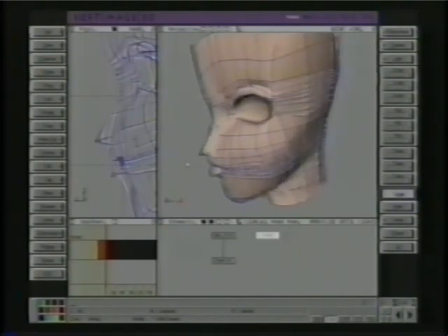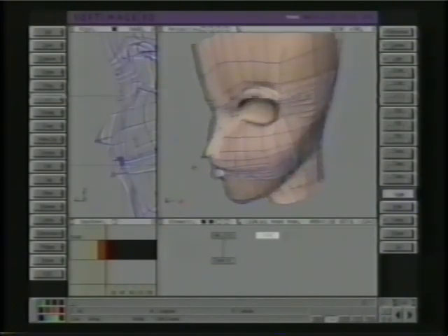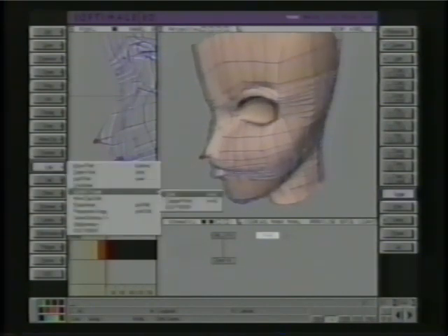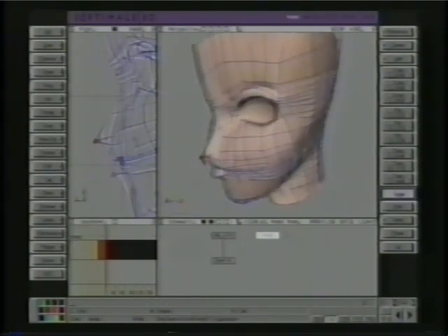Like I mentioned in the curves section, with a NURBS curve or NURBS surface, you can weight the surface toward the control mesh vertices. So for instance, I'll select those two, go into Edit, NURBS Weight, Tagged Points, and then drag. You can see that get pointy around it. So I can create a pointy area, or I can weight it away from it and actually push it away from the point, from the vertices.